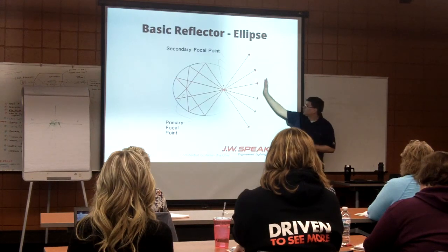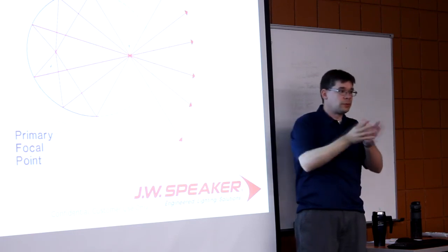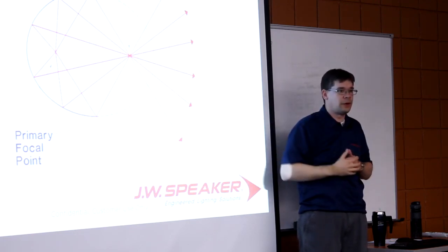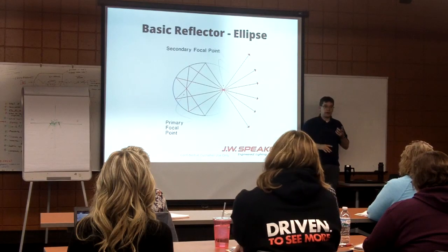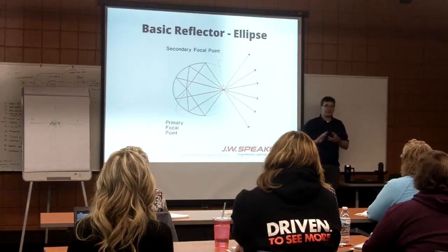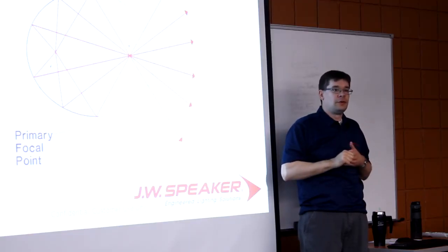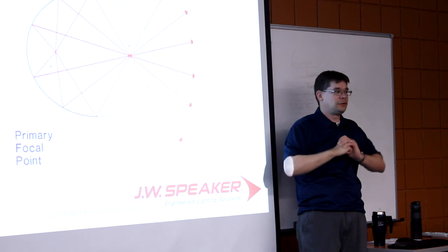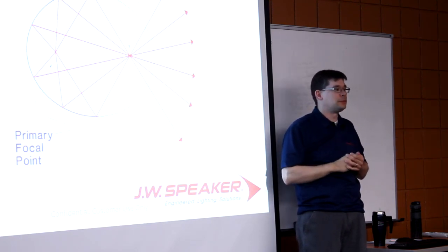And then what we do is we put a lens out here that's focused on this image. So we're collecting the light, putting it at a point, and then making an image of that point out on the road. So in real basic terms, reflector optics bounce light around, and lens optics, we use refraction and internal reflection, and that's what we do when we design optics. We take light and we bend it or bounce it to get it to go where we want it to go. In really, really simple terms.